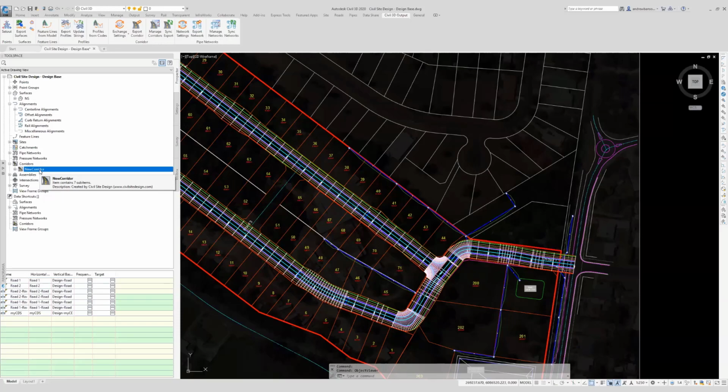We might delete some regions or baselines, but we recreate the corridor, using the same object, if you like. So if you've added labeling or created a Civil 3D surface from that corridor, when you run sync, that won't be broken. All those references won't be broken.